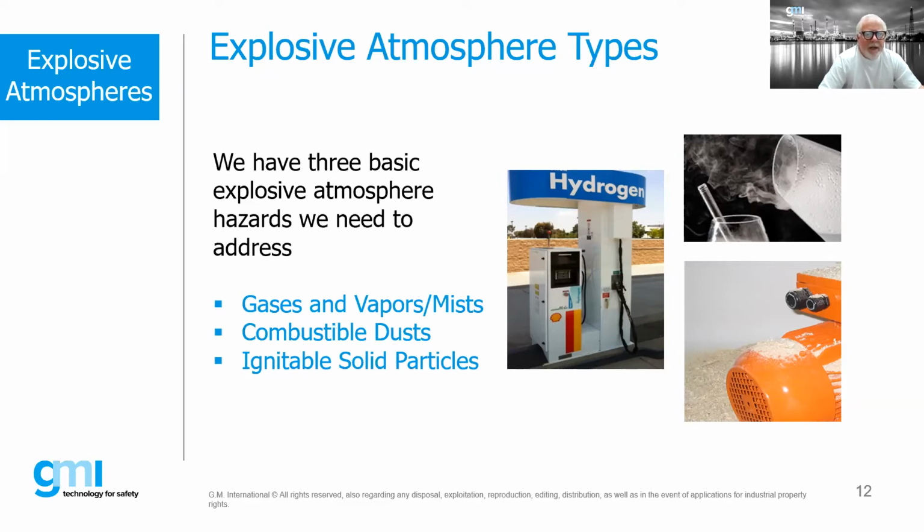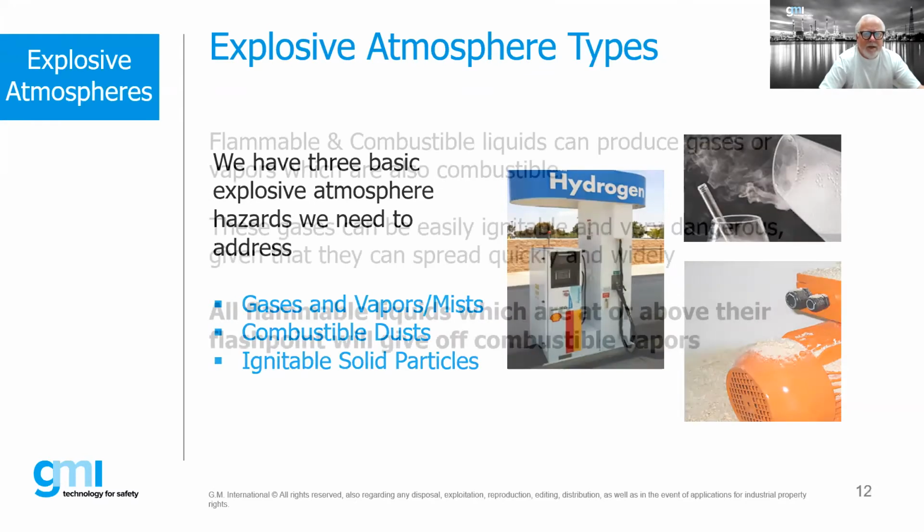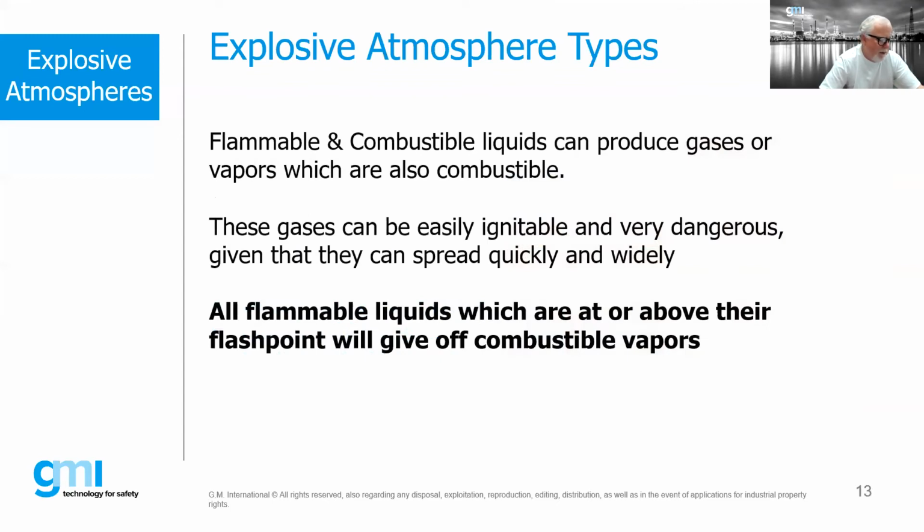We have to define what the explosive atmospheres are. They can comprise gases, vapors and mists, which are the most common ones we think about, but also combustible dust and ignitable solid particles. So we have to understand what it is about the hazard that we need to address when we start selecting equipment and dealing with all of this.